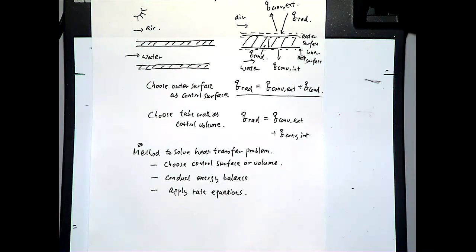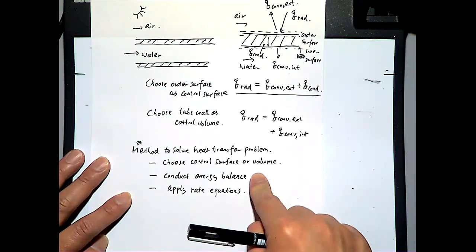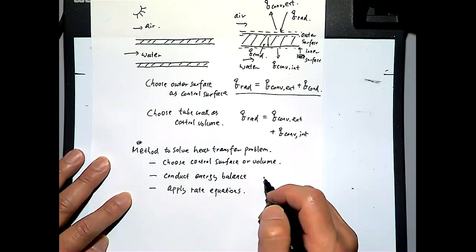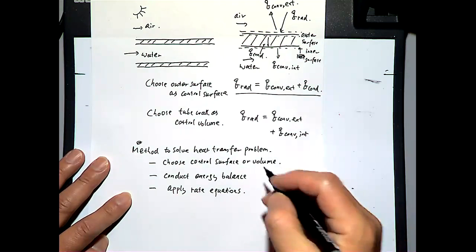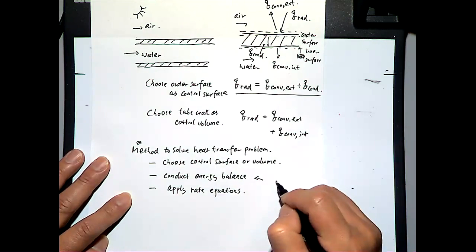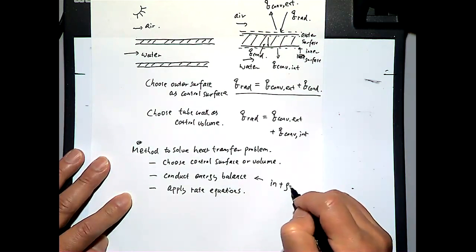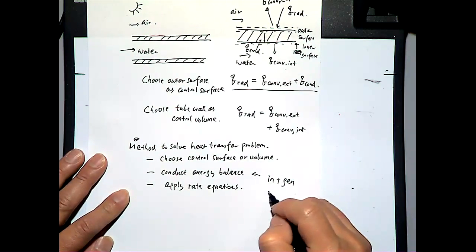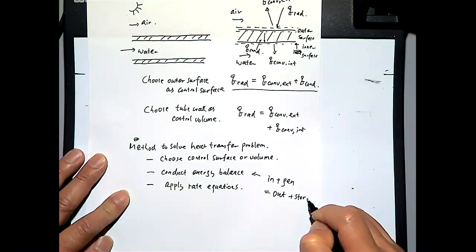Right? I should say we call the energy balance the first law. Energy balance certainly is more than the first law. The most general principle is actually applied to not only energy but to all the properties that are conserved in the process. It should be written as the things coming in plus the things that are generated within the control body or control surface equals the things getting out plus the storage within your control body.